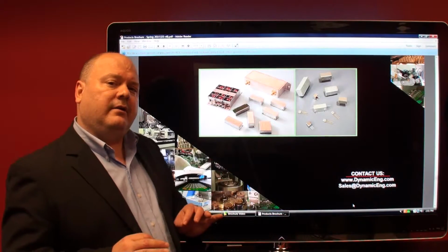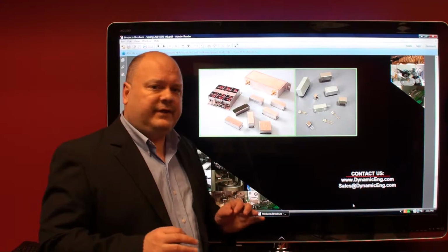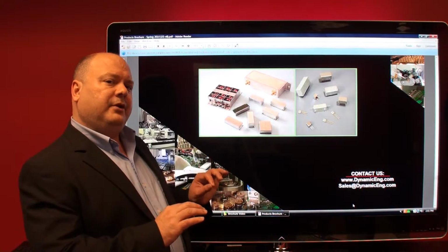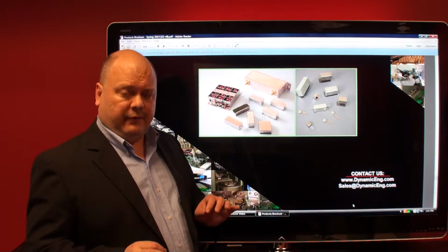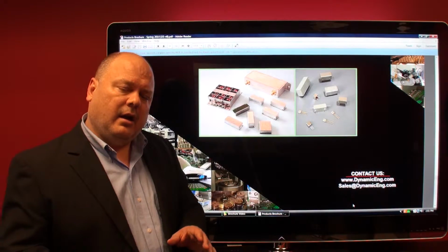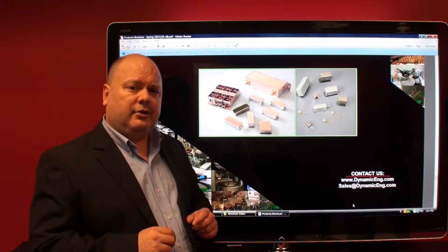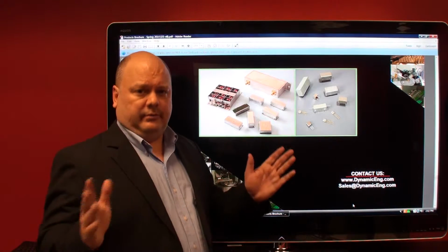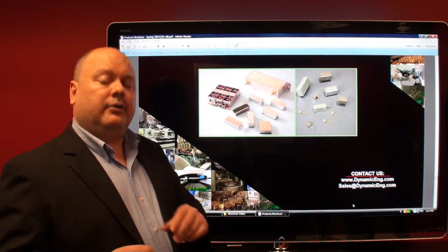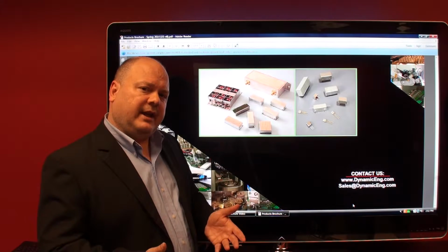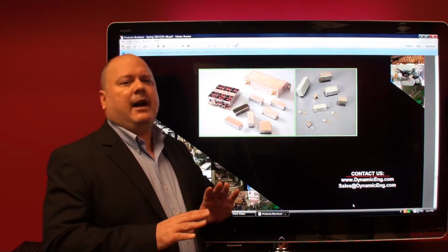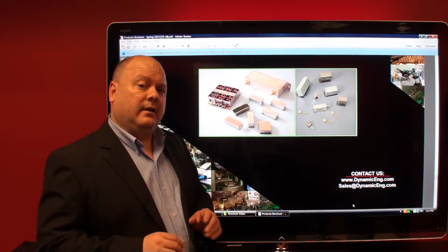So there's a lot of work done with technicians, all with 15, 20, 25 years experience in the business, who match up the crystals with each other for a given design and a given frequency. These crystals, as well as the final assemblies, are cooked at elevated temperature many weeks in total. A couple weeks for the crystal, a couple weeks for the crystal filter assembly. The reason being, in quartz crystal technology, cooking at elevated temperature takes out of the product a lot of the frequency shifting that could go on.